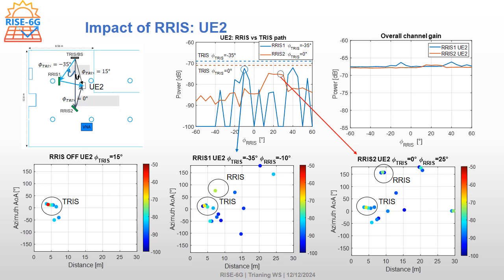This angle of arrival estimation was possible thanks to a virtual array. So here we show how with the transmitting RIS we can highlight the direct line of sight. And when we don't have the line of sight, what we can do is to use the reflecting RIS to activate some new paths that are clearly well identified in amplitude, in distance, and in angle, of course. And this kind of data has been used then for evaluation of localization properties and localization algorithms employed.